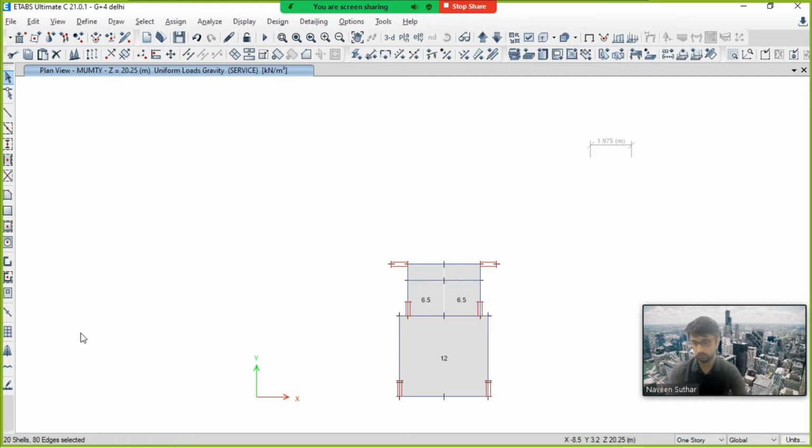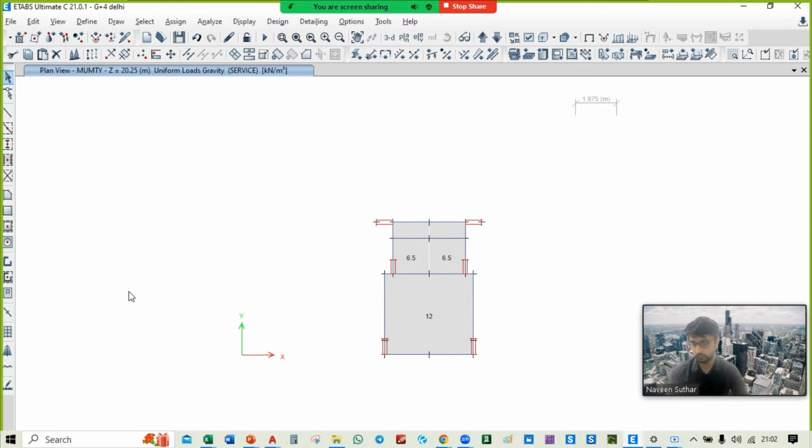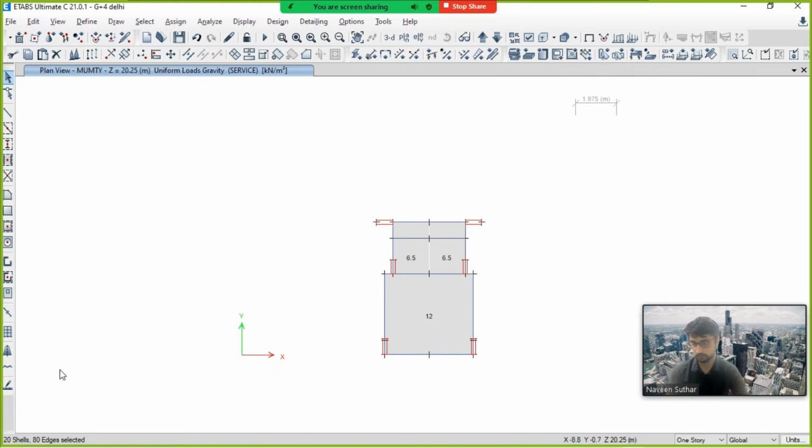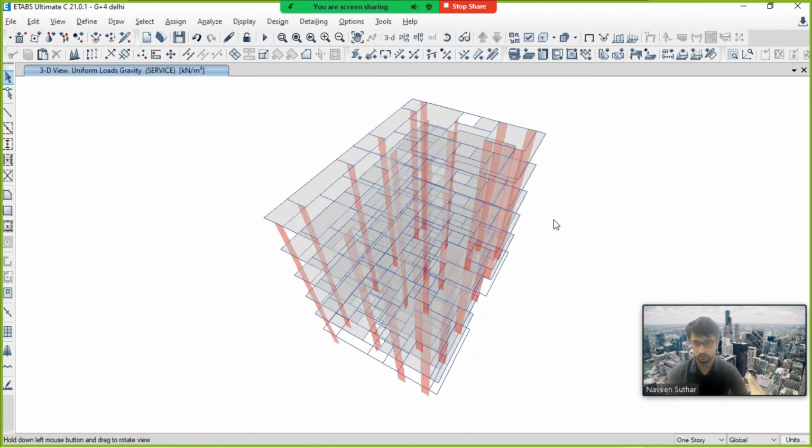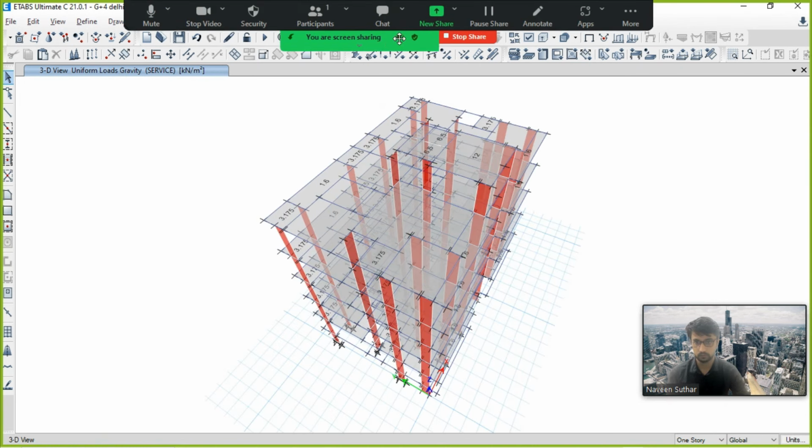Okay, you can see, select this. So here you have unselected this, so you got only 20 cells here at the left bottom. There are only 20 cells because we have to take the area of the lift at the above. That's why we are not deleting this, and delete. You can see we have deleted this one and this one at the Storey.